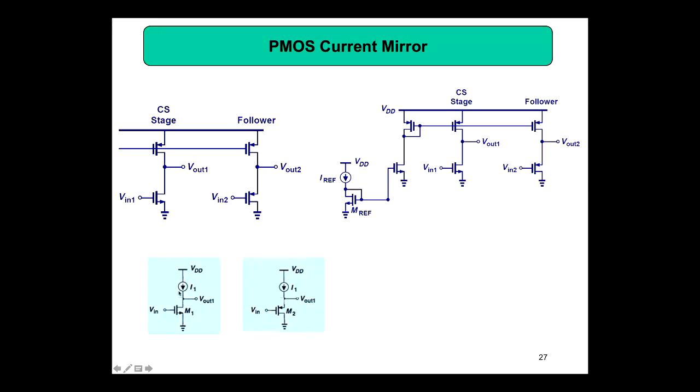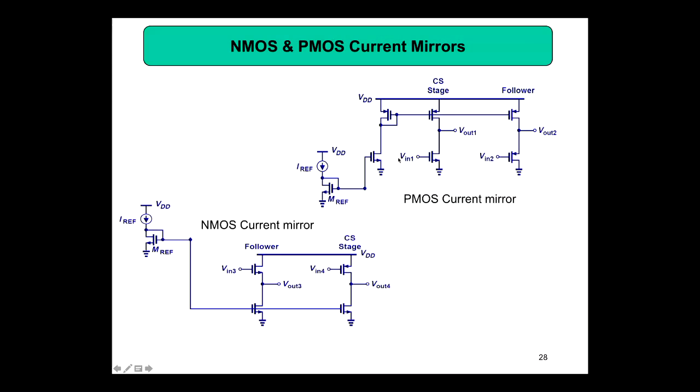And when you have PMOS, as I said, you will be designing a PMOS current mirror, and then you will connect the PMOS current mirror again to an NMOS current mirror for biasing it. When you design a chip, you have both: PMOS current mirrors and NMOS current mirrors. So the problem is you should be able to combine both. Combine both means you have only one band gap reference, and you may have PMOS circuits, PMOS based amplifiers, NMOS based amplifiers, PMOS transistors or NMOS transistors in the design, or PMOS current sources, NMOS current sources, but you don't want to have separate connections.